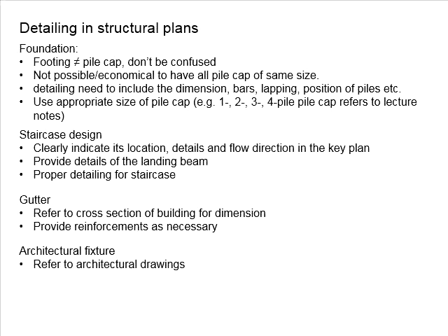It is always a good practice to standardize the thickness of the staircase throughout the entire building in order to avoid the contractor overlooking the dimensions. You need to properly arrange the reinforcement bar, design it, ensure it passes all the technical requirements, and clearly indicate, for the top reinforcement bar at the support, where the reinforcement bar stops.